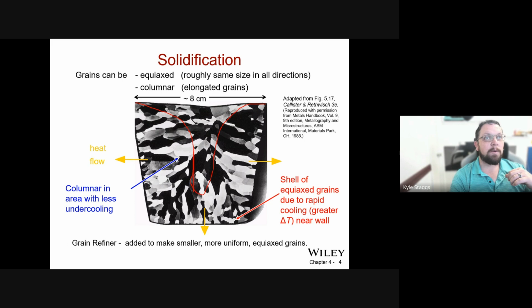So the longer grains will fill this region, the shorter grains will be here, and you can typically see different layers, often if it was cast in this direction. So this one appears to have had some fairly rapid cooling up at the top, so more rapid air cooling, and the center is where all of the heat remained for the majority of the time. So that's what's going on here.